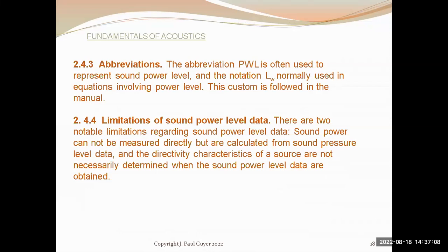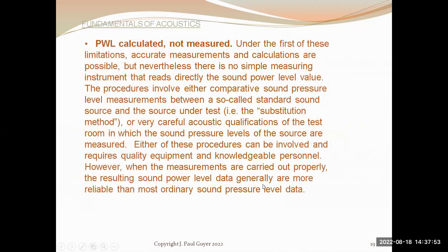A point of somewhat of information is that sound power level cannot be measured directly. This is because you have a point source producing a sound, but it's radiating out with these sound vectors of different magnitudes in different directions in a 360-degree three-dimensional environment. And there's just no way to construct a sound power meter to capture all of those vectors. Just a little piece of information. It's not something you can measure.